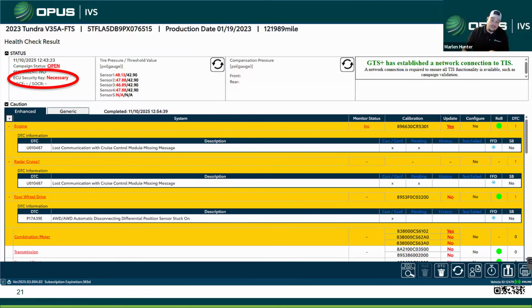You cycle the key off, back on, and start the car up. Once you put it in reverse, you'll see you now have the red and yellow grid lines. And when you turn the wheel, they'll start sweeping left to right. So essentially all that's telling you is the radio needs to learn where center is, or where the steering angle is.